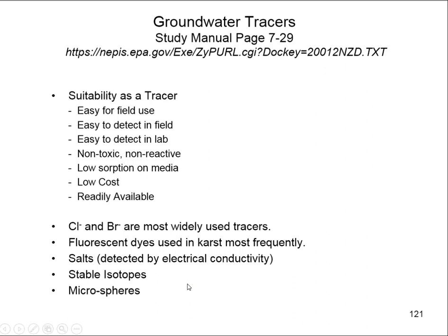So whatever ratio there could be worked out to see what your groundwater movement is like. And then the microspheres. For this, if you have a reservoir, you can use those plastic spheres to prevent evapotranspiration. But you could also use them in karst, where you have disappearing streams, and you count the number you put in and what you get out at your output, and get an idea of where the water is going that way. So you can use a lot of different things in that way.